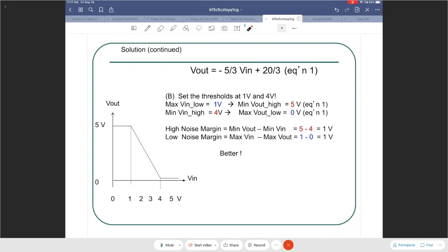So if you are, say, purchasing logic gates and you want a logic gate that is of higher tolerance, then you would want to look at the thresholds that are acceptable to that logic gate as input low and input high, right? So we don't program that. It is a consequence of how it is manufactured.